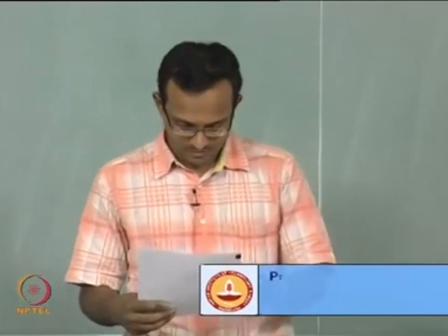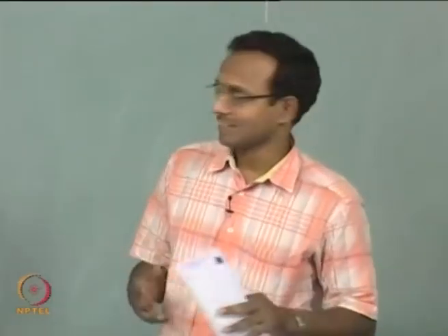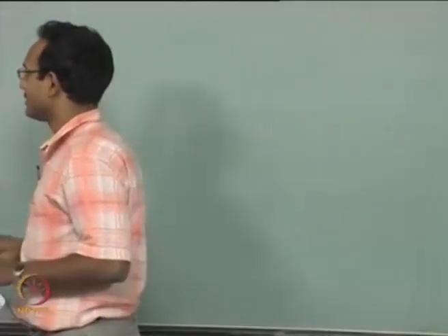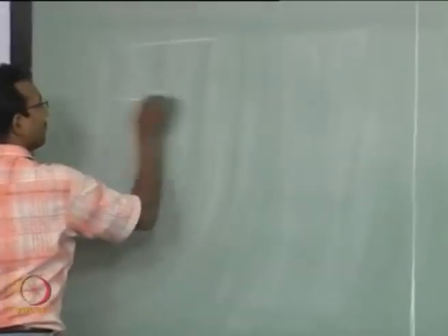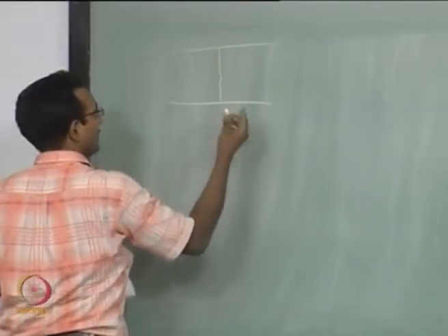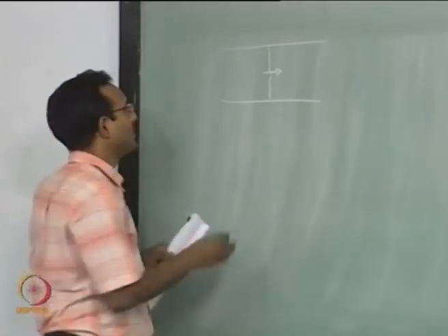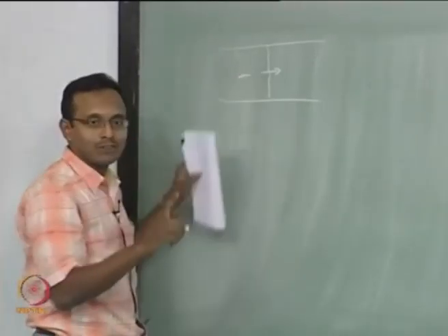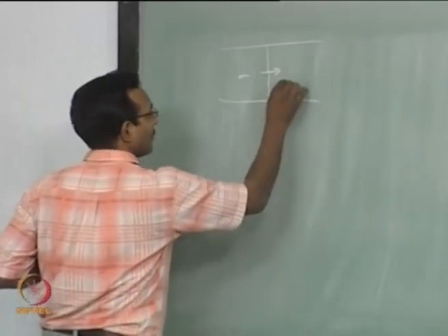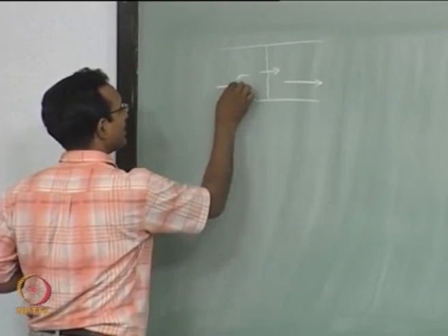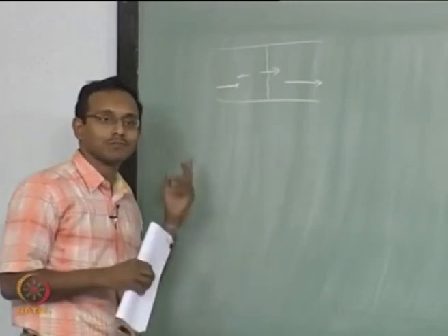Hello everyone, welcome back. We looked at simple one-dimensional waves last class for the expansion process, and we said that we have to look at it as if I have a flow, and if there is a wave going like this, the induced flow part alone will be like this. If the flow already has a big velocity, the induced flow should be added to it, and it will be slightly lesser; only this much will be the final velocity. This is what we saw last time.